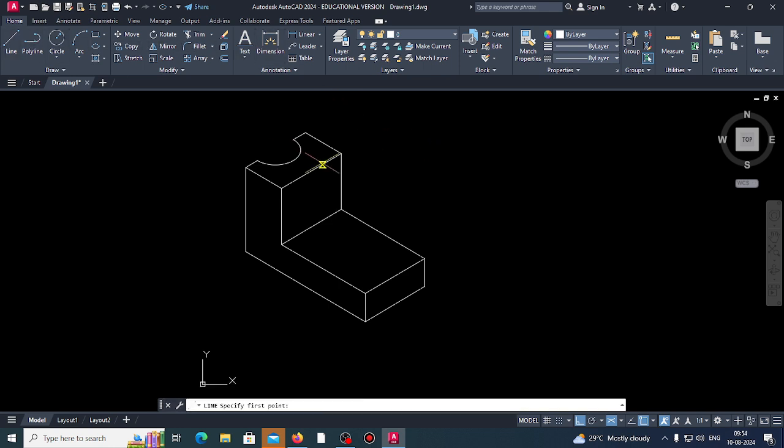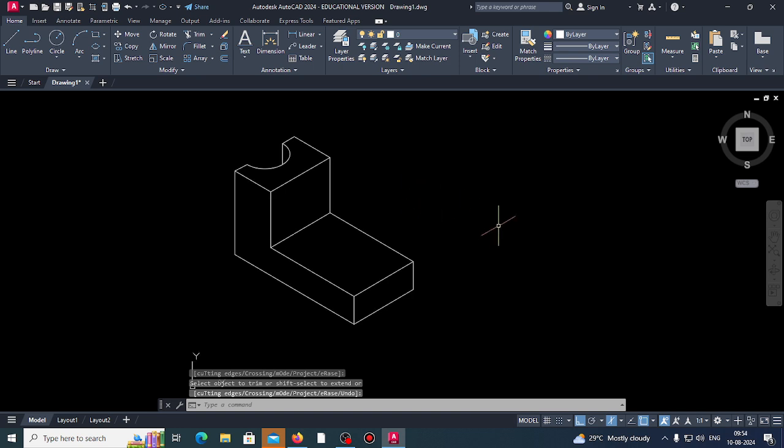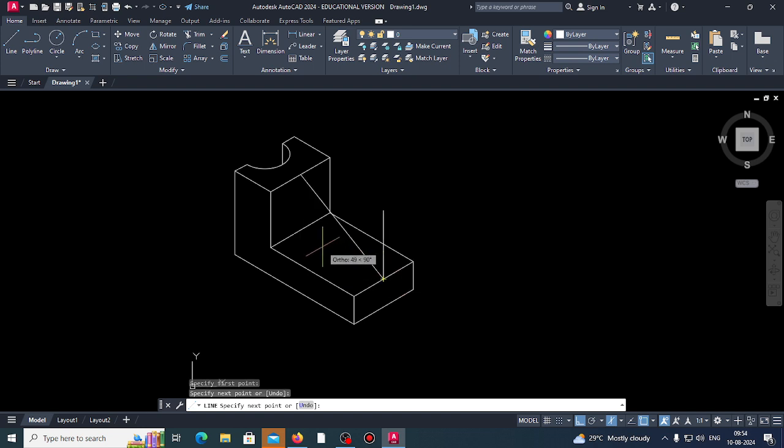And in addition, in isometric, you zoom in and draw this edge that can appear. ISO plane F5 and trim, and a small vertical line is to be drawn there. Okay, and coming to the rib, you can draw in the middle, center to center one line, and again ISO plane F5.